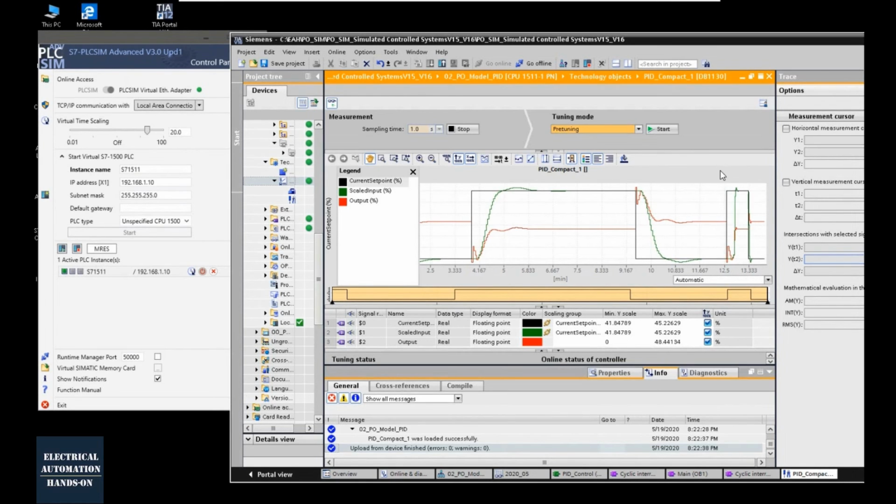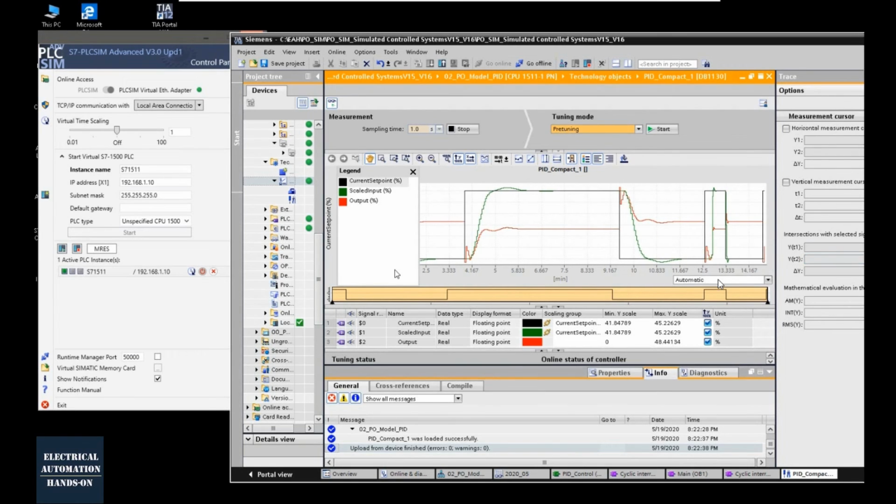With this faster response, you can adjust your PID very quickly, because usually to fine-tune the whole set of PID parameters, we need a couple of cycles or more than 10 cycles, which really takes a long time. With this scaling function, it can save us tons of time waiting for the system process response and the transition time. And more importantly, using PLC Sim Advanced, we do not need to change the logic and the program, so this speed up operation will not cause any potential program issues.